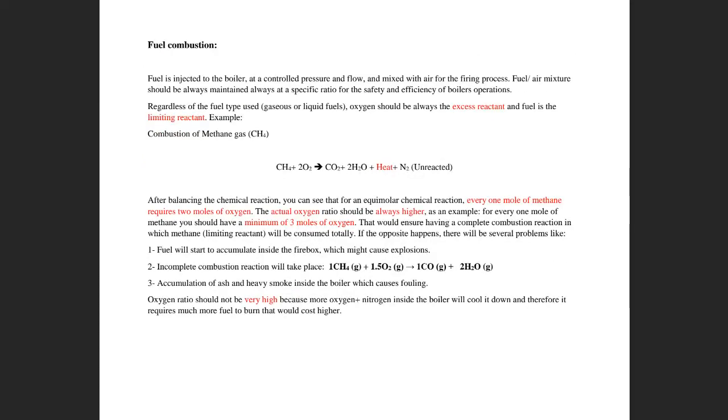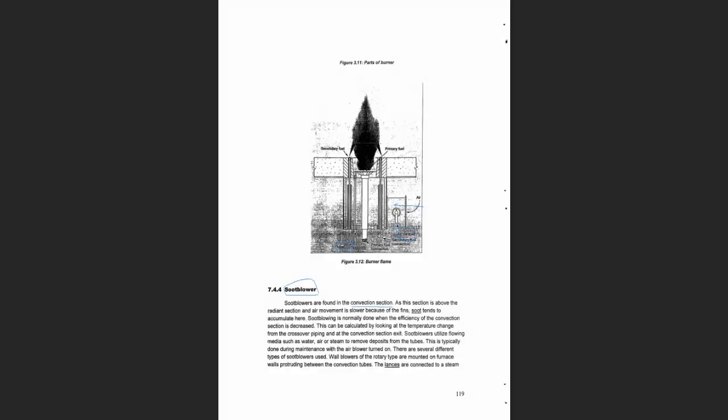I'm not sure, but I believe I mentioned that before. I mean, briefly, I talked about the soot blowers. Usually, you will find soot blowers in the boilers, because along with the gas fuel, they also burn liquid fuel. And with liquid fuel, you will have a lot of smoke, and probably a lot of ash and carbon accumulation.